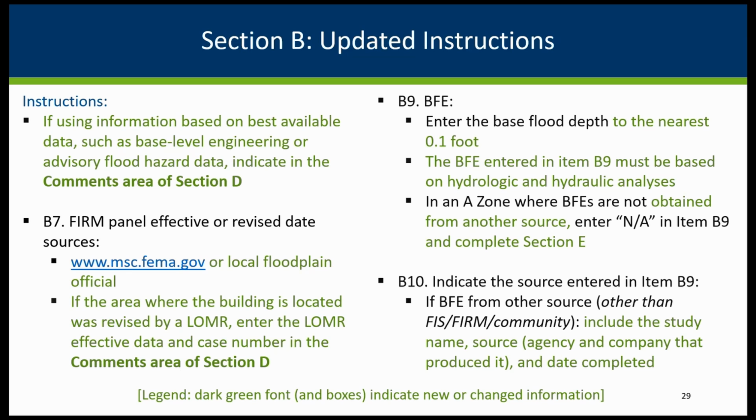So it can't be based on approximate methods like contour interpolation. It has to have H&H analysis associated with it. And this last part here, if you're in a zone A where BFEs are not obtained from another source, enter NA in item B9 and complete section E.